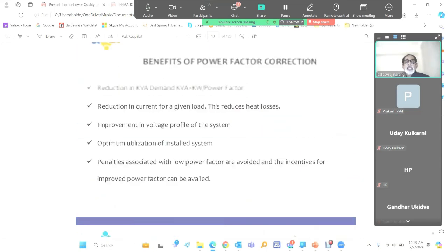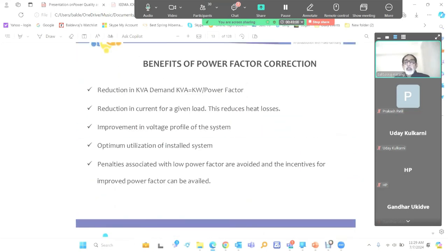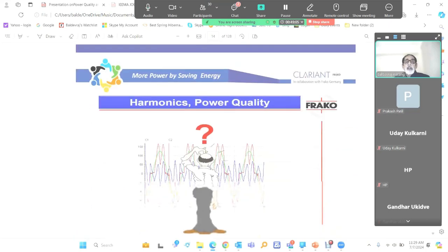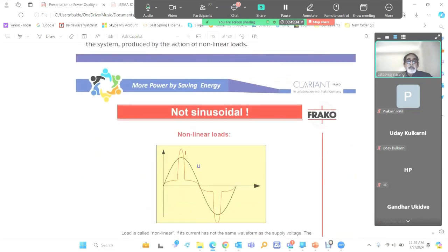So these were the slides on how to improve the power factor, reduce the demand, and improve the billing through reactive power compensation. Even harmonics are getting built into the tariff structure, so this is also part of the savings. Then we have harmonics in the systems, because most of the loads today are non-linear. About 70% of loads are non-linear, which introduce harmonics into the system. And these harmonics create a lot of issues, which we will come across later in some slides.